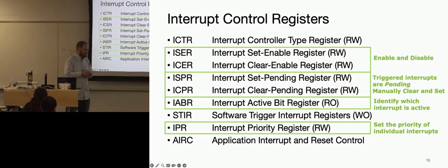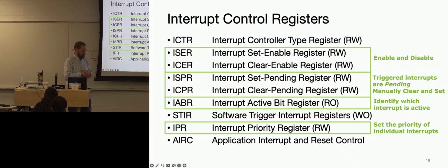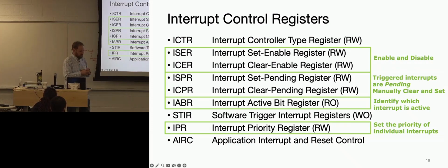I used MSP430s back in the day, which is a smaller microcontroller, to do really low power things, and some of those were random. You didn't know what bit state some of those registers were going to boot into. And so you better go and reset them to something known as soon as you wake up.